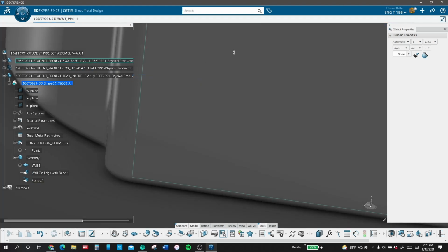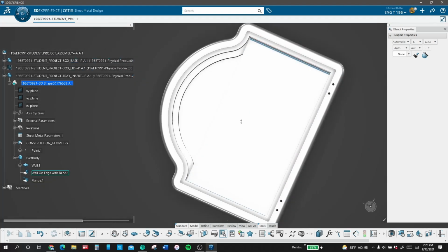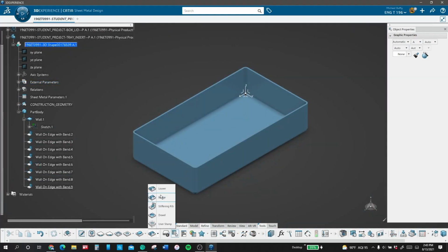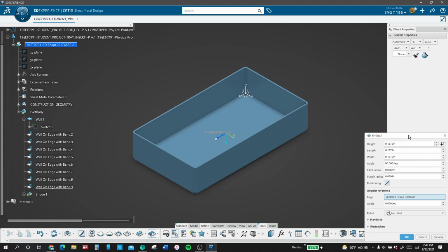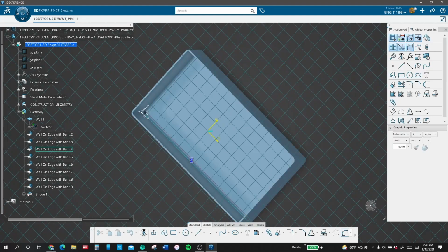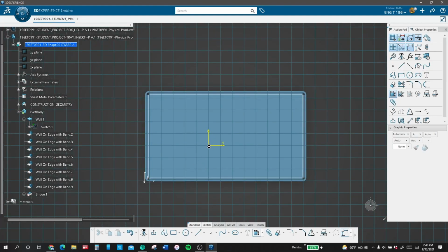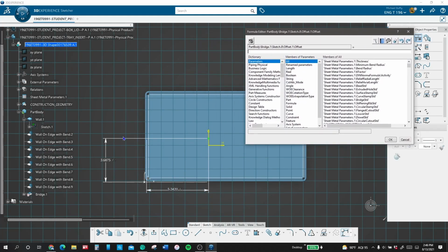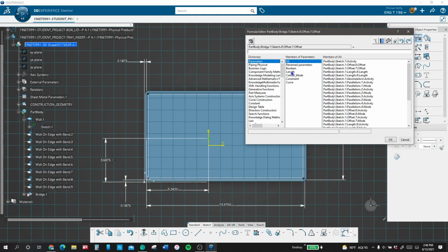Make some sides for the tray. And there it is, finished with the 4 sides done and 4 bends into the corners to round them off. You see a little gap in the corner down at the bottom because it's sheet metal. Now what I'm doing here is I use the bridge feature to create a little handle to be able to lift the tray out with.